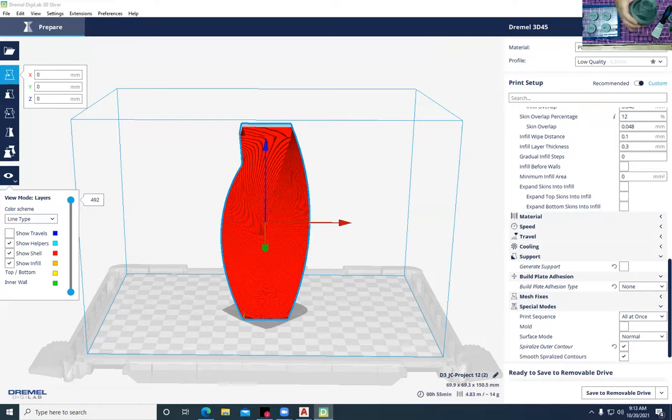But when we had a radius, an internal radius like this right here, we were getting failures. A couple of people had that same failure, where it just can't work with that kind of a slope. So it starts to print in the air and it loses the adhesion. What was neat about this was it kind of corrected itself and then finished it at the top. So that's how our models turned out. The ones that were more linear turned out really great.